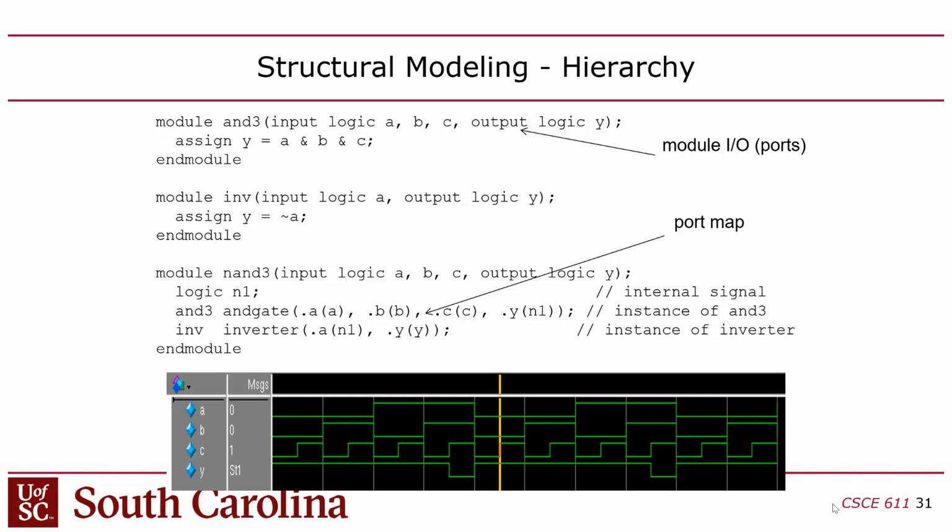So when eventually I write a test bench for this, I'll have something called expected Y and then actual Y. The expected Y is a value I'm going to just type in manually myself, and the actual Y is what's coming from the component. So the whole idea, and this is how you test all these designs. If you design your CPU and it doesn't work, you have to start drilling in, looking at waves, and making sure things are as you expect, right? So the methodology that you'll use is you'll have your RISC CPU, and you'll simulate it, and it's supposed to be running a program that puts values out on the hex displays.